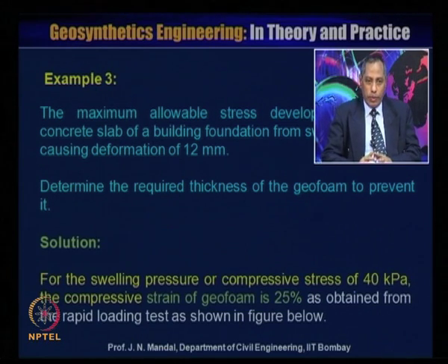So there is a solution. For the swelling pressure or the compressive stress of 40 kilopascal, the compressive strain of geofoam is 25%, as obtained from the rapid loading test as shown here.